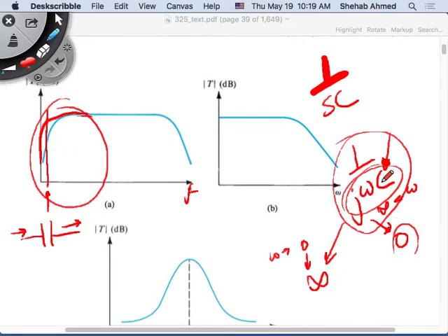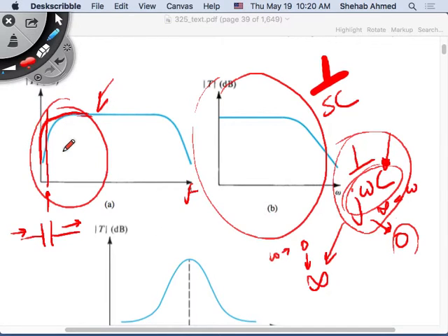Can you do that on a chip? You should not do that on a chip because you will have a chip that's this big, and you cannot do that, right? That's why integrated circuit amplifiers, like an op amp, are typically DC coupled or direct coupled. Discrete circuits that you make, you can design as capacitively coupled because you can put a large capacitor outside on the board in discrete fashion, right? These have applications and these have applications, right? So the next chapter will be on direct coupled amplifiers. One example of a direct coupled amplifier is the op amp.